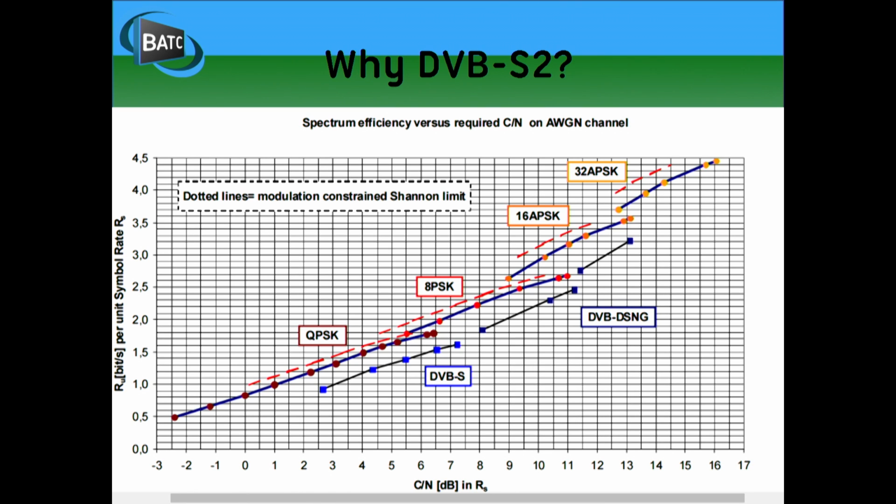When we were doing the original planning, AMSAT-DL were insisting it was going to be DVB-S2. We were quite sceptical, but the first few days really proved that the stations who ran DVB-S2 rather than DVB-S were the ones being more successful, because every dB really does count.